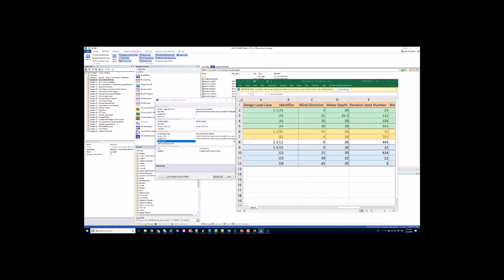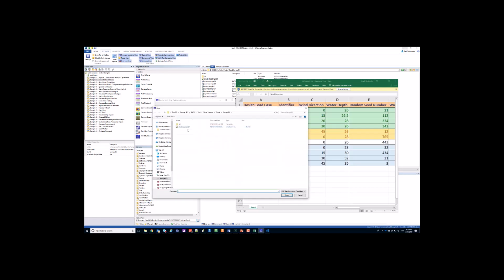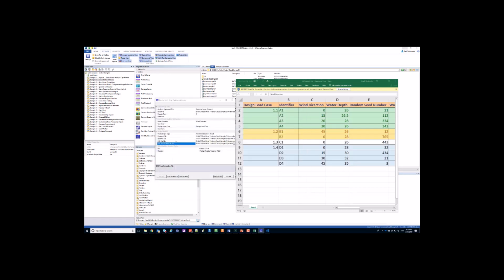It's going to ask for the DSC DAT file and DSC transformation file. These are output from the mode shape extraction and analysis. They're going to be used to generate the DSC output. So we have the DSC DAT file and DSC TRS file. And then here we're going to do the DLCs. These are the design load cases. This is how we're going to set up all of those other variables.